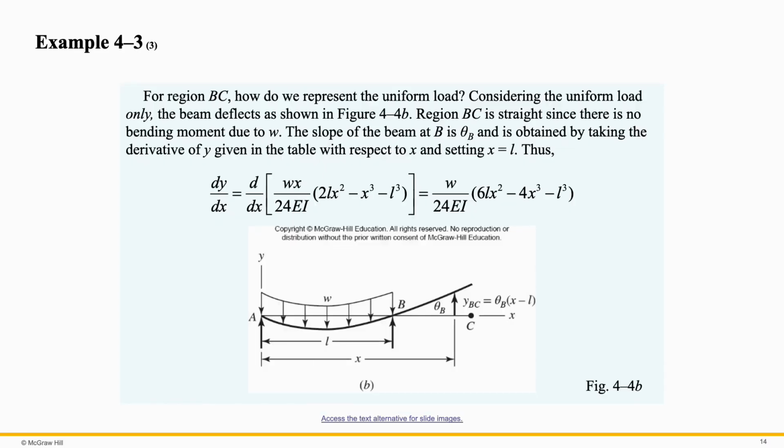Let's analyze the effect of distributed loading in more detail. This is our slope function. We know that this was obtained on the previous slide, and you know how to obtain the slope function for this distributed loading. But please note that this distributed loading exists only between A and B. Between B and C, we don't have any distributed loading.